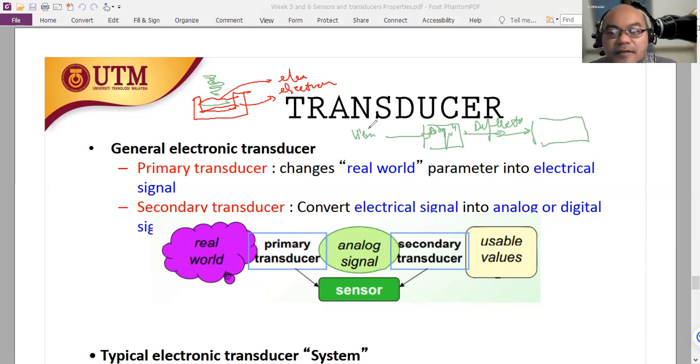So let's say the delta here, it becomes deflected downward due to this vibration, for example. And the deflection delta is converted into delta R, a resistance change, for example, by strain gauges. So we have strain gauges attached on the surface of this diaphragm. Afterwards, this delta R is further converted into what? Into delta V, a voltage change, by what we call a Wheatstone bridge. Remember.